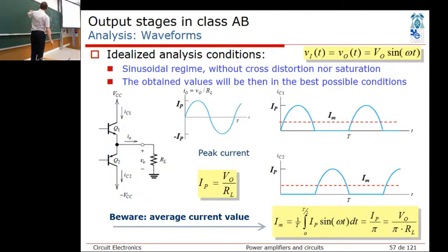And if you do the math with that one, calculate the average power. Do we calculate the average power somewhere? Yes, we do. So basically, the peak current is simply the peak voltage divided by RL, as long as it does not saturate.